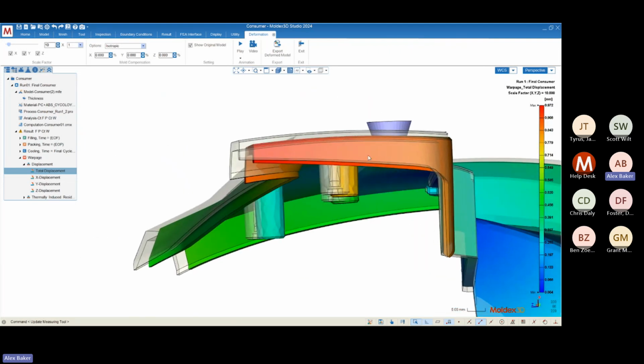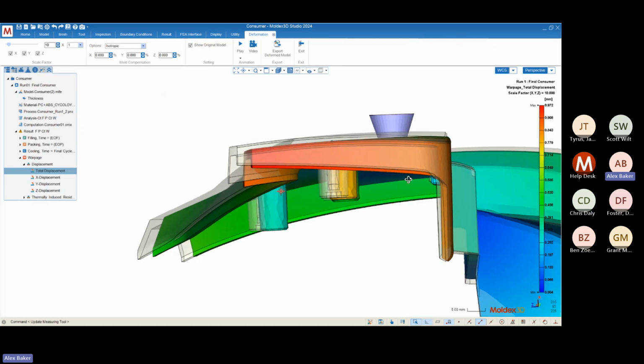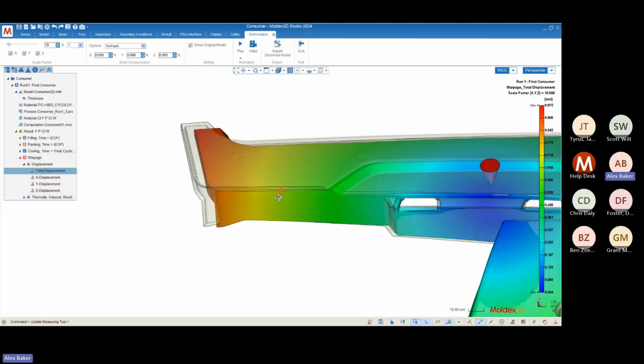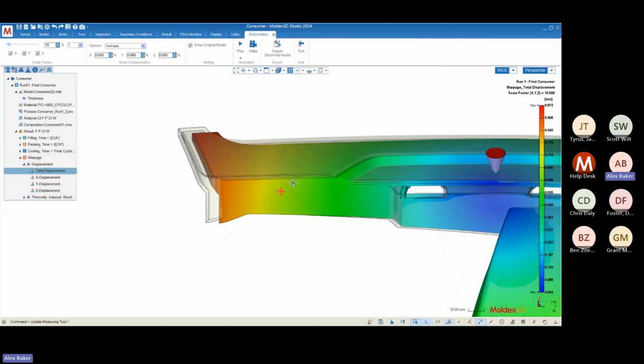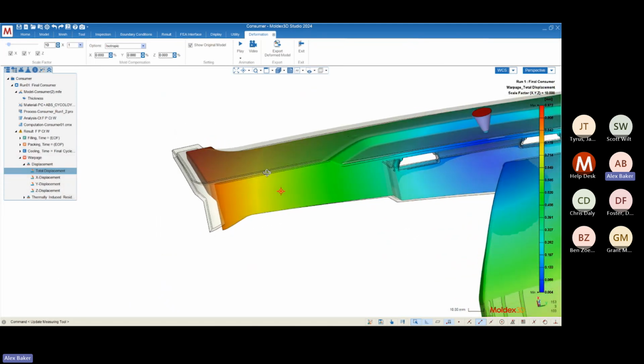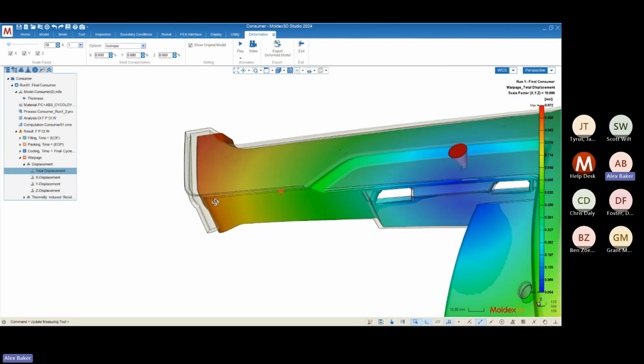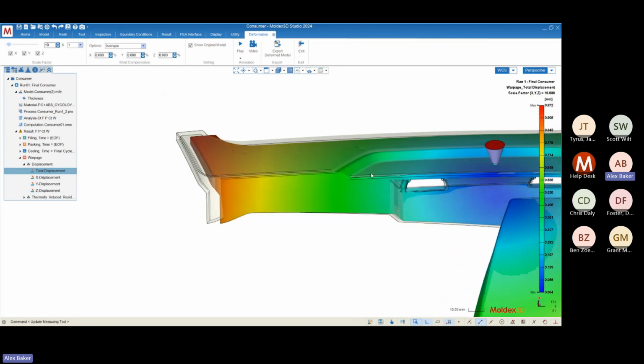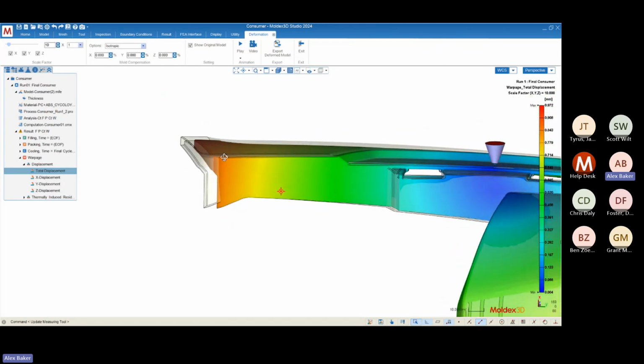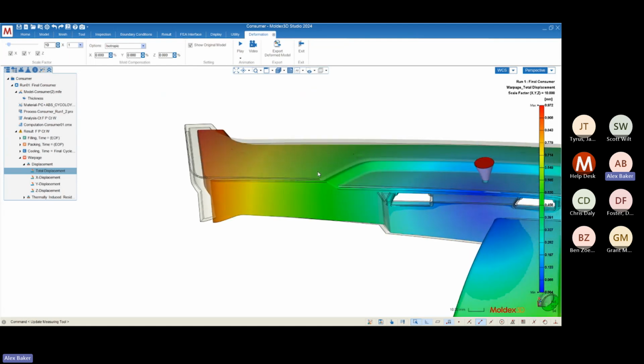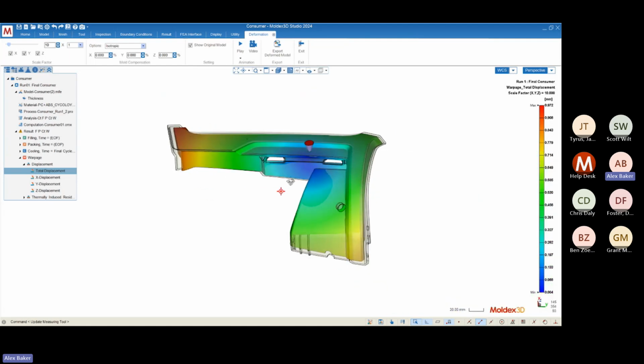And we don't really see a whole lot of movement, maybe a little bit towards the right side in the Z direction, but really not too much there. So I would say that this is mostly just linear shrinkage, right? So there isn't really too much deformation happening here. It just kind of looks like this is all shrinking towards the center of the part.